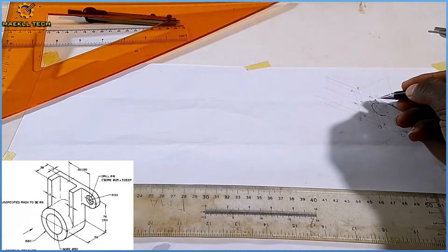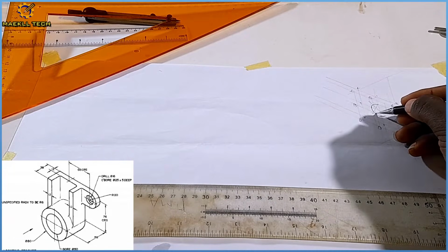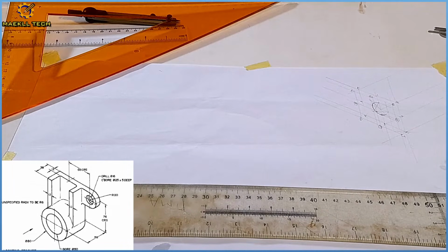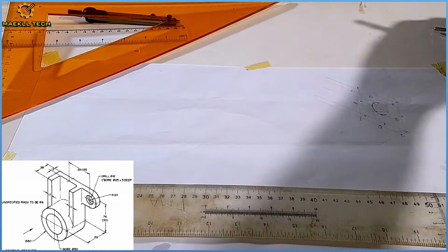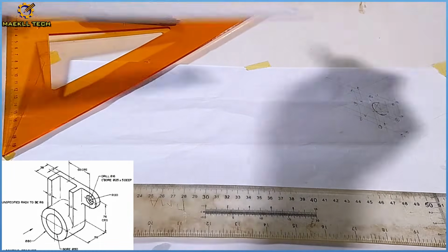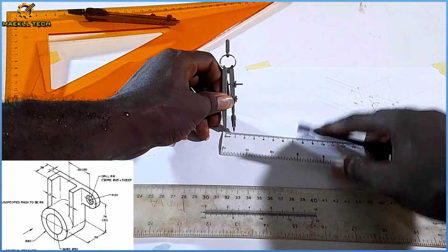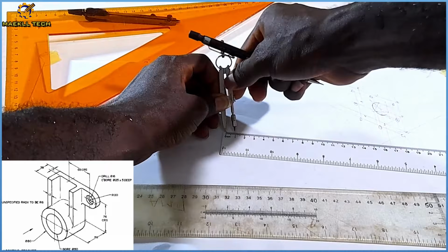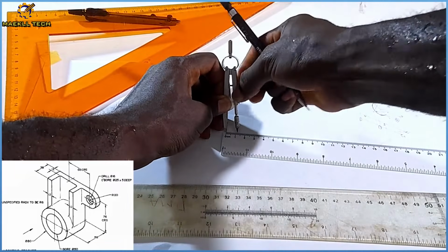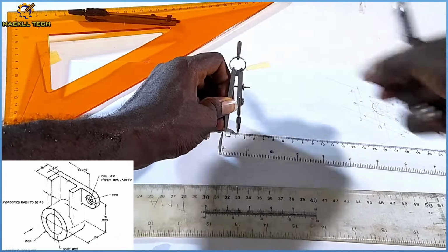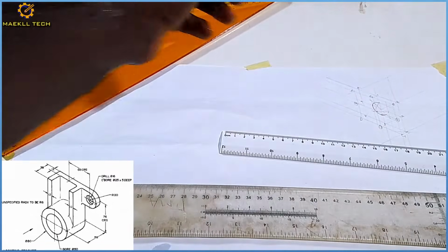So, my new midpoint in the front here is here. So you need to figure it out. Now, after that, the diameter, thickness of 5. So we have a diameter of what? Diameter of 25. That would be a radius of what? Radius of 12.5. So with my compass and my ruler, like this, I try to measure 12.5. So let me take this as 12.5 on my compass.